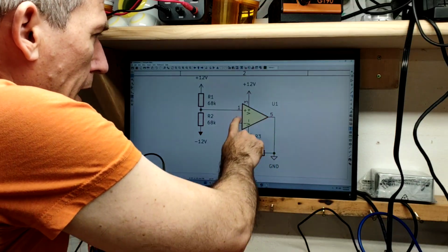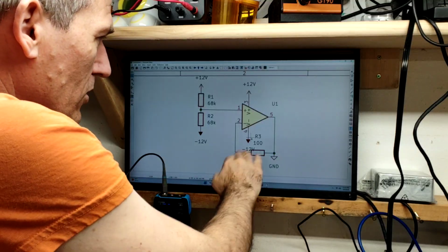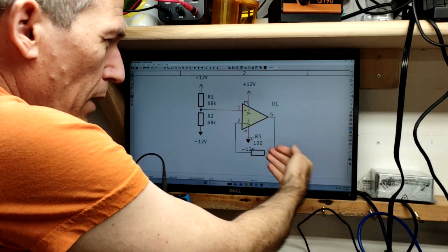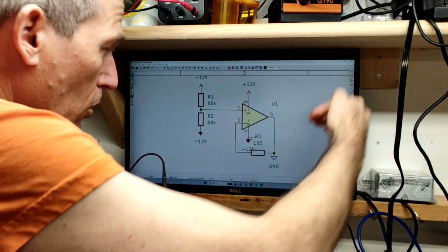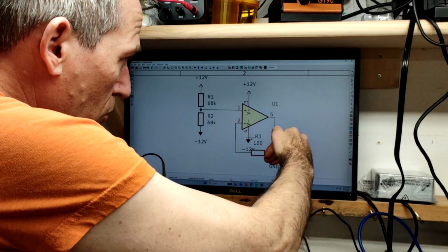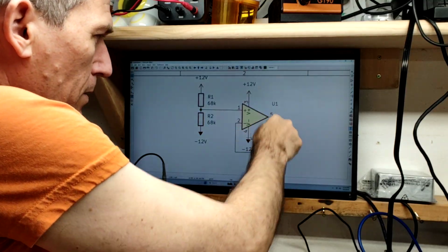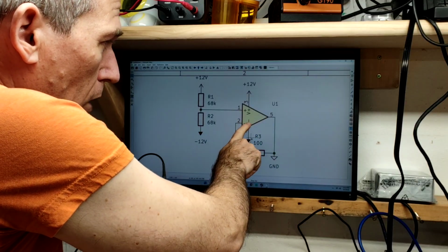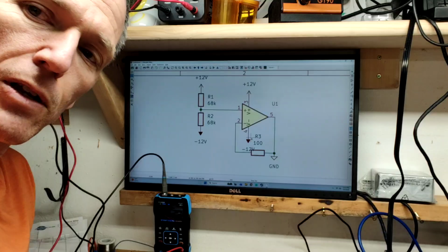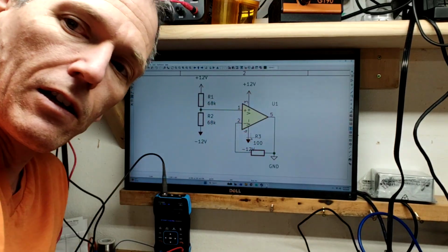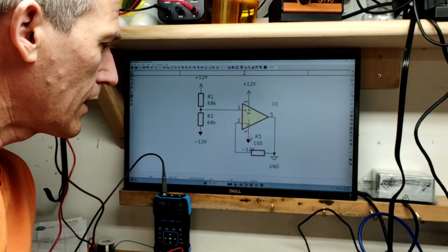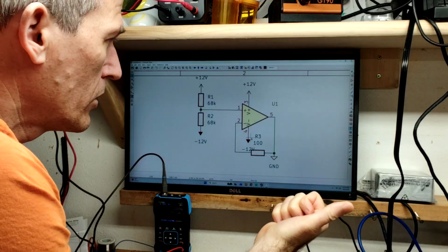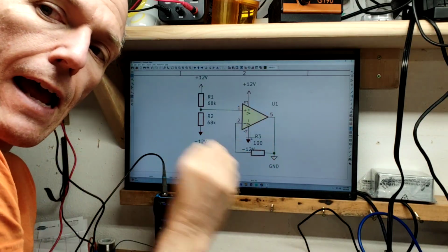It has negative feedback. This is a tiny little resistor. We can almost pretend that it just doesn't exist. If this is ever too high, if something is dumping positive voltage into the ground, with some current flowing in the conventional direction towards ground, it's going to bring this voltage up, and so this op amp is going to try to drive it down, because if this is higher than that, then we're going to drive negative voltage. And the symmetrical thing happens the other way around. So this is how we can construct a ground with high impedance, so that when we're dumping current in or pulling current out of ground, either way, this op amp is going to keep that ground at 0.